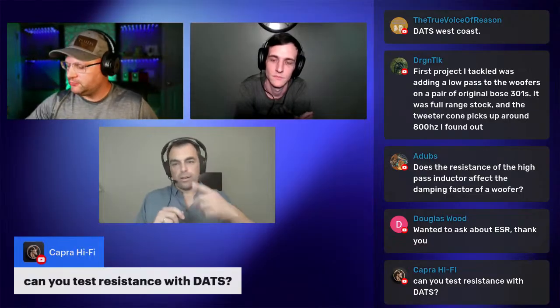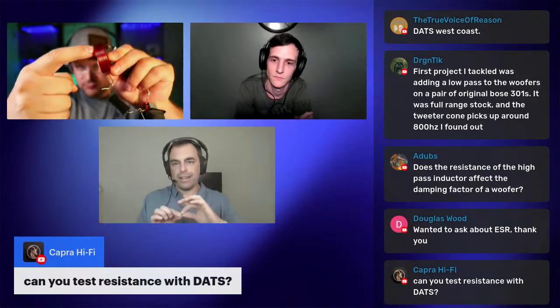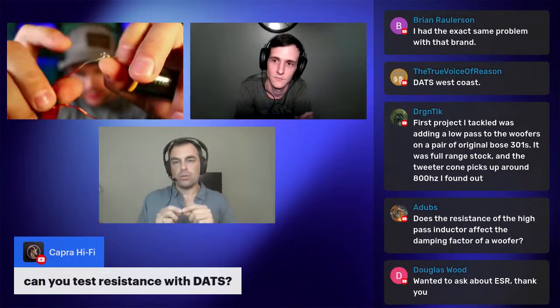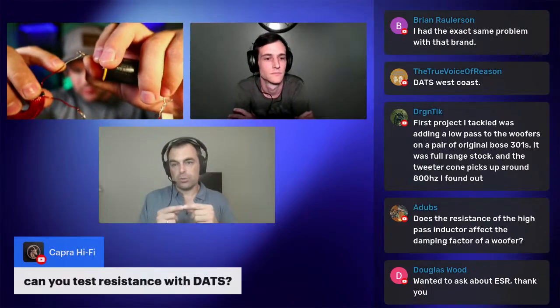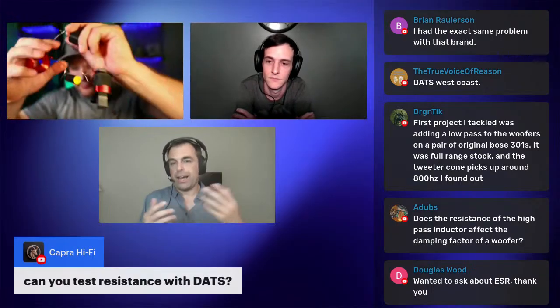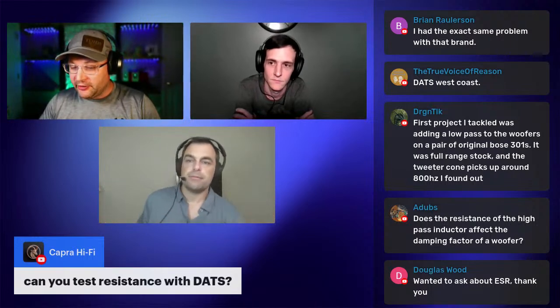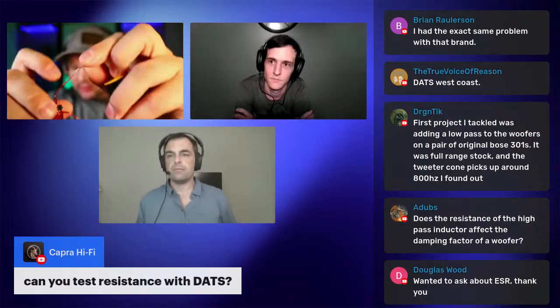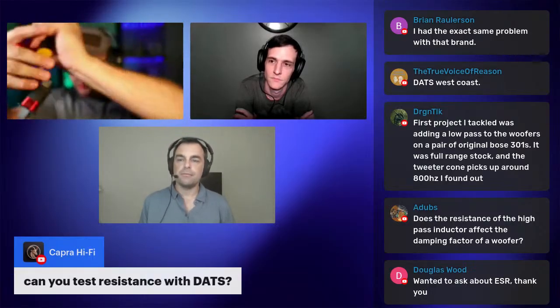Like I said, it's just a bunch of wound up wire, and it has a coating on it. That red enamel coats it so it doesn't short. But if that is scratched when it's getting put together, it'll short circuit, and it'll short out half or maybe all of the coil, and then it's useless. The other thing is people will cut these down and they'll try to solder to the red. Oh yeah, you can't do that. Because then they wonder why their circuit's not working. Well, that's why.